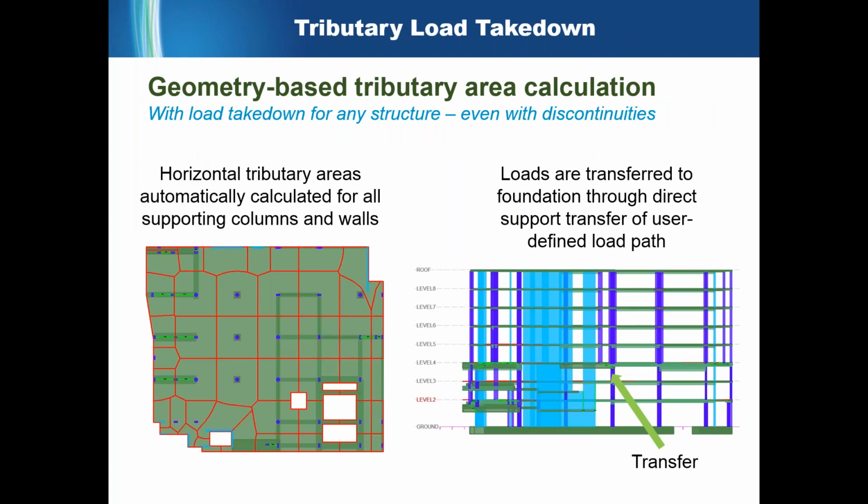The tributary method is really important, because we found that the vast majority of engineers at least do some form of calculations, usually hand calculations using Excel, to calculate these tributary type loads. And what the program does is it calculates very quickly and effectively the geometric tributary boundaries of your floor system, and transfer conditions are identified, and the load path is very clearly shown and it's something that you can control.